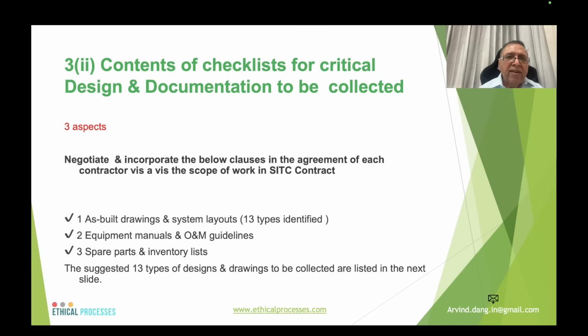Clients, contents of the checklist for critical design documentation to be collected. Now these are as-built drawings and systems layout related, 13 types of document identified, equipment manuals and O&M guidelines, spare parts and inventory list. Now, this is based on my practical hands-on experience when such clauses were not initially incorporated. So there was a lot of difficulty in getting the as-built drawings because the final payment had been made, and therefore the contractor actually charged extra for these drawings and system layout to be made available.